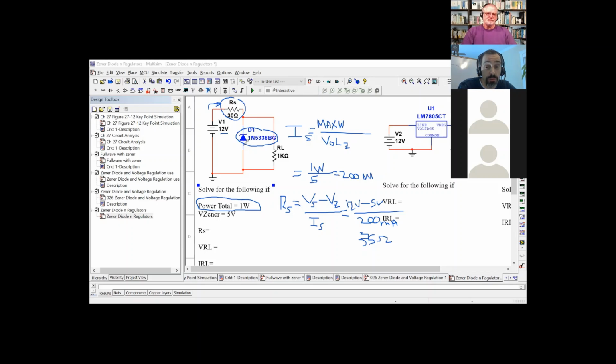It's always the voltage. Let's say you're fixing a board and you looked at the schematic, and it said it was a 6-volt Zener. They give you a part number. All you have to do is go into Mouser Electronics or one of those and say, I need a 6-volt one. And you get it. But let's say you decide you're going to get a 12-volt one. You just blew up your circuit right beside you. You could blow things up down the line. So always pay attention to that.